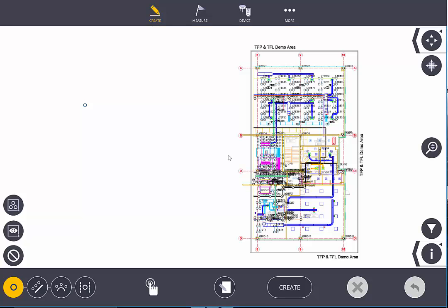What Point Manager allows me to do is several things. I'm only going to talk about basically the list view and how we can organize and create a list using the Point Manager. But it allows us to do a few things. We can select points by window picking, current view. We can clear the current points that are selected. We can offset points from a line, from an arc. We can create a point in the center of two lines. I show that in a separate video. We can place a point anywhere. Of course, our input form button. But the main thing that I want to highlight in this video is the filter button, which was not there in previous versions.